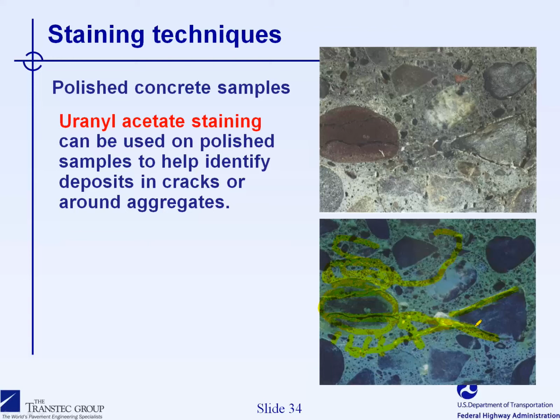Yes, thank you, Benoit. I'm not aware of any specific cases where ASR has been implicated directly in pavement buckling. I have heard anecdotally of some cases with CRCP pavements where they've had some distress that was somewhat sudden, and that was potentially due to ASR, but I don't think there's any definitive proof. Most of the issues that we observe with pavements tend to be degradation at the joints, which ends up being kind of the end game in terms of serviceability. But in terms of the actual buckling, I'm not aware of any specific cases where that's occurred.